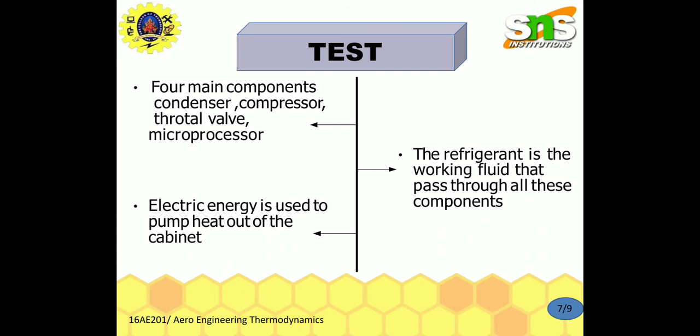Air is most often the working fluid, as there is no condensation and evaporation intended in a gas cycle. Components corresponding to the condenser and evaporator in a vapor compression cycle are the hot and cold gas-to-gas heat exchangers. For given extreme temperatures, a gas cycle may be less efficient than a vapor compression cycle, because the gas cycle works on the reverse Brayton cycle instead of the reverse Rankine cycle. As such, the working fluid never receives or rejects heat at a constant temperature.